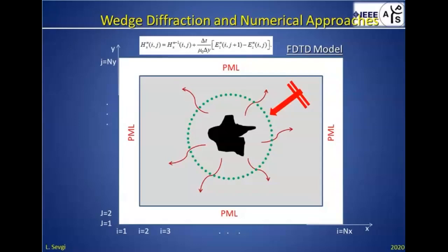So your signal, electromagnetic plane wave, but pulse in the time domain, hits the object, and transient effects around the objects occur. Scattered time domain fields around the object occur within a few nanoseconds or picoseconds. Then you record those time domain scattered fields with a number of receivers.